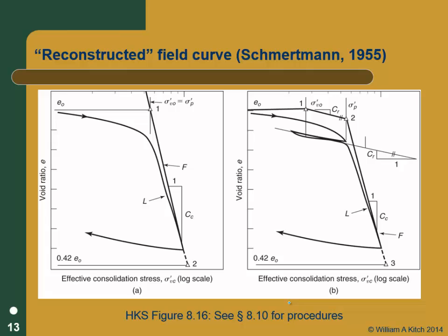And I know that for fairly stiff soils, because I've seen my students do this for our undergraduate lab, you get really bad answers if you go out. Around here you have these partially cemented silty sands and stuff, and you go out and do tests on those. If you do Schmertmann's method on those, you're just going to have an answer that doesn't make any sense at all. Because if you plot them in arithmetic space, you find out they're pretty linear.